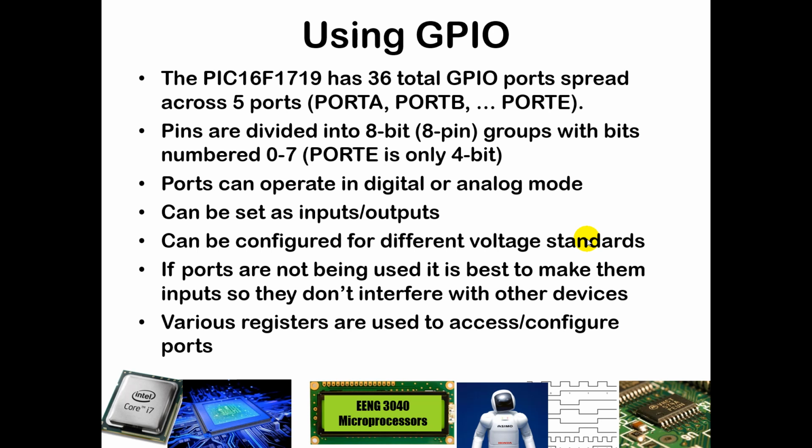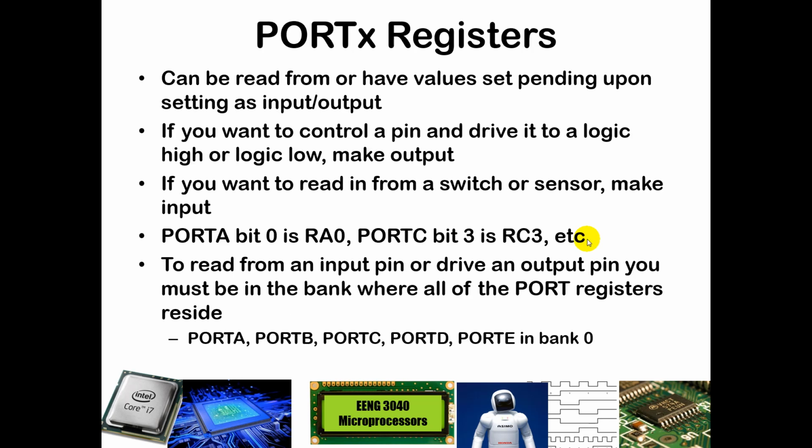In general, again, if any of those pins are not being used, it's a good idea to make them inputs so they go into this high impedance state, and we'll see that illustrated in just a couple slides as to why that's important. And so you can use several registers to access those ports and to configure them. So the first registers that I want to talk about are the port registers. I have just the X there as a placeholder because this information applies to port A, port B, port C, all the way up through port E.